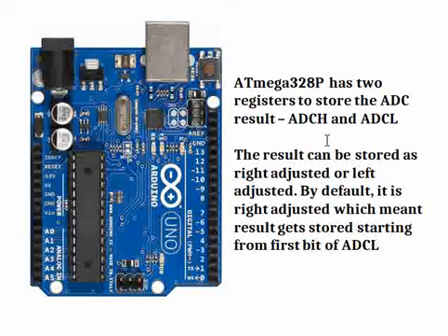And then let us assume I just gave a minimal voltage of 4.8 millivolt. That is a very, very small value, right? If you represent it as 16 bit, it would be 0, 0, 1 or 1, 0 or whatever based on the value. So whether that result of 1, 0 will get stored in ADCH or ADCL is a very, very important point. We need to know that correctly so that we can convert that register value into the actual value to find out what the analog voltage is.